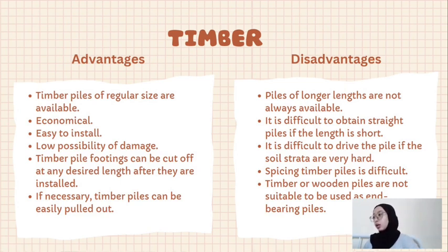So there are advantages and disadvantages of timber piles. For the advantages, timber piles are available in regular sizes, economical, easy to install, with low possibility of damage. Timber pile footings can be cut off at any desired length after they are installed, and if necessary, timber piles can be easily pulled out.